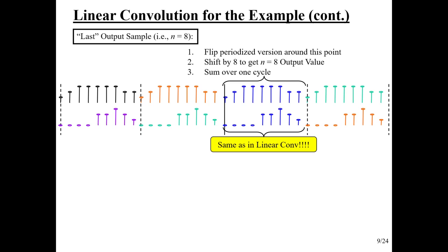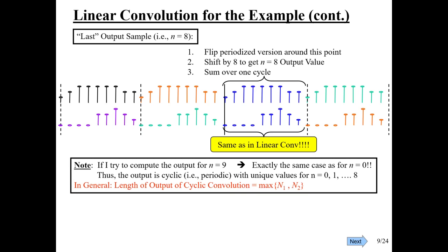And as you'll see, some of those actually turned out to be all the same as linear convolution. Exactly like this position is for n equal to 8. Look at this. These all end up forming 0 products, and these form 5 products that are exactly the same as in linear convolution. So the n equal to 8 term is correct. And in fact, n equal to 7, and I think maybe even n equal to 6, maybe a few others. So there's going to be some that are wrong and some that are right. And that's weird.